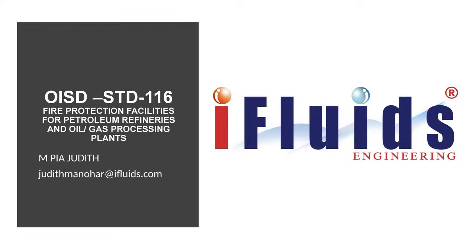Ma'am, one more question: fire and gas minimum detection value, the minimum value with respect to the flammable. I understand it is based on the LFL level. That depends upon the company criteria. As far as India is concerned, there is no such defined criteria. In general, a low alarm is provided at 10 or 20 percent LFL. A high alarm is provided at 45 percent, sometimes 60 percent LFL. LFL is the lower flammable limit for the hydrocarbon vapors.